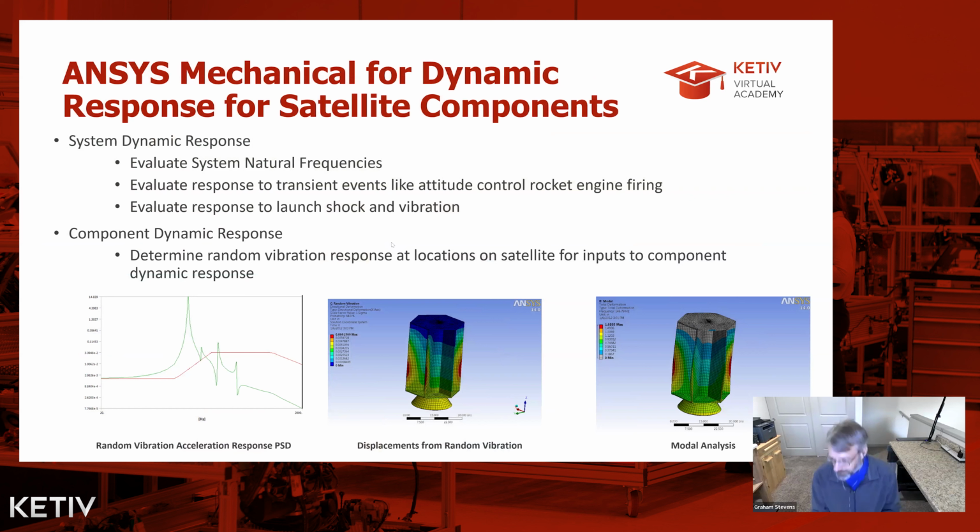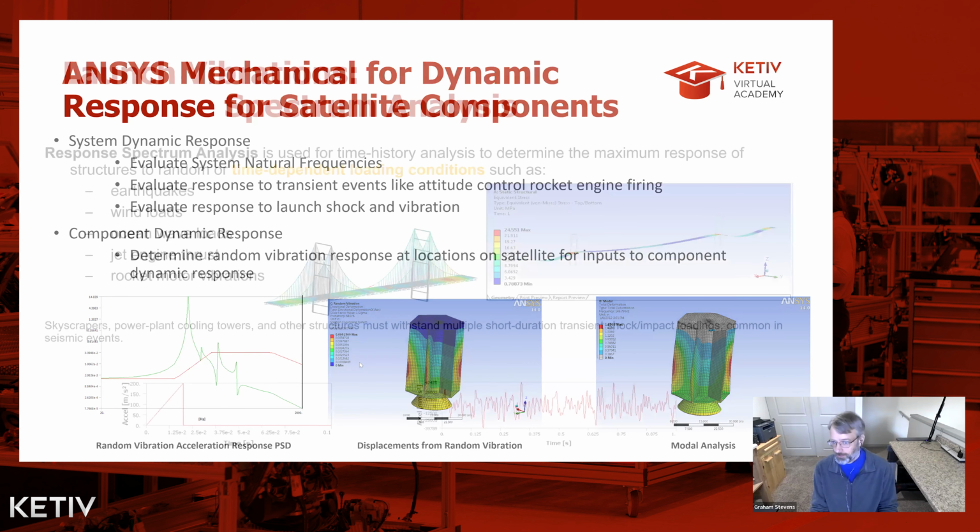So when we think about launch dynamics, and how do we tell whether our electronic board is going to survive launch, typically users will start with Ansys Mechanical, and there are some dynamic analyses you would start with. The first is a modal analysis to see what the natural frequencies of the structures are. And then you might do a random vibration analysis. And in particular for launch, you would also jump to something called a response spectrum analysis.